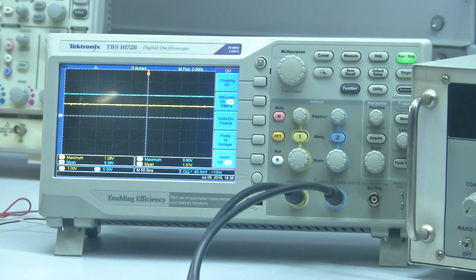With this we can understand that the selection of resistance in a non-inverting amplifier configuration is a little tricky, in the sense of the availability of resistors close to the required gain. However, since the input is directly connected to the positive terminal, the input impedance of the complete system is equal to the input impedance of an operational amplifier, which is very high. And you can see that it is following our requirement, the gain is almost close to 10.